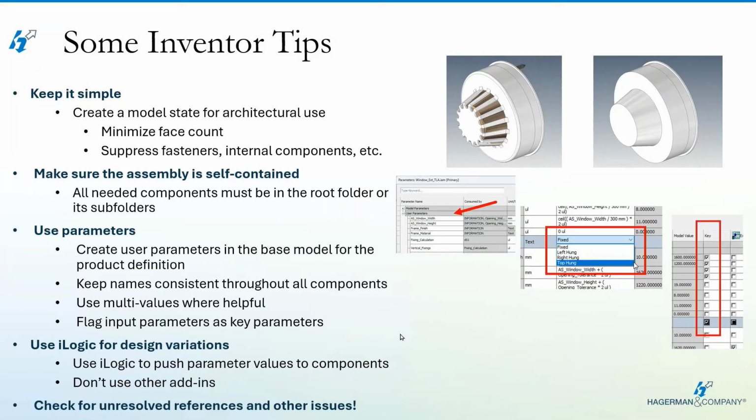Make sure that you've checked the file before you publish it. Right. Make sure to flex it through some changes in values at the Inventor level. That way you can be confident your Inventor assembly is going to work before you start worrying about adding the information that the customer is going to see. Okay.